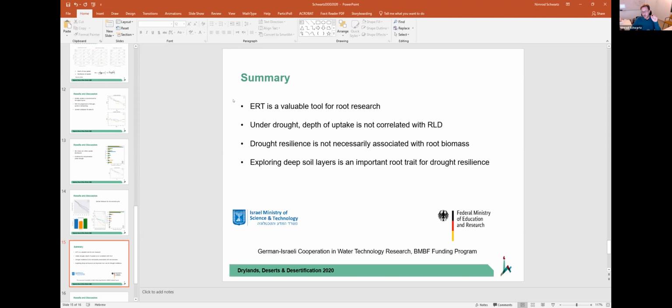So every time that we took an ERT measurement, we also measured the water content using TDR, and we used these data points to fit the petrophysical relationship, and not something else that we take to the lab and find the Archie parameters or whatever. So this is really based on the data. I would say that this is data-driven fitting.